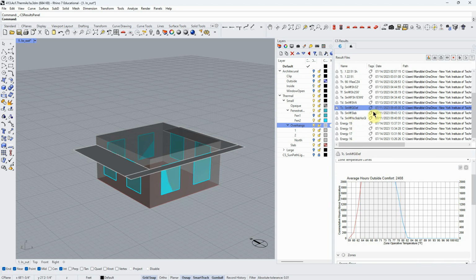We may remember back, if you look back at the other videos, when we had that initial configuration, it was a building, it has windows and an envelope. We set our mechanical system so it would maintain a certain comfort zone. That still doesn't always happen, because comfort is, even if the dry bulb temperature is what you've set it at, you might be next to a cold window and be uncomfortable. So there's ways we can model that also. And so we saw that there was a fair amount of time when we were out of the comfort zone.